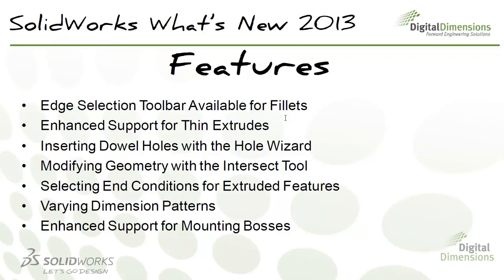The next thing I'm going to be going over is varying dimension patterns. This is available for feature patterns, and it's available for circular and linear patterns. So you can change the spacing between instances and also the size of instances, and you can actually modify the instances one by one directly in the pattern.